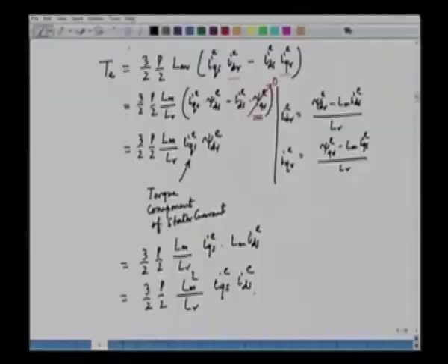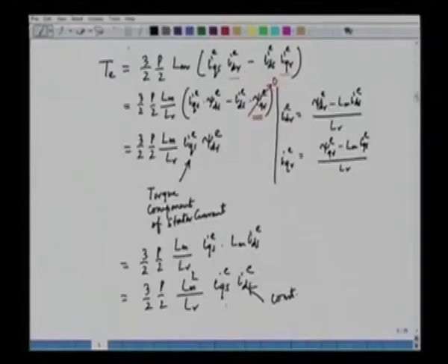we keep IDS constant, because if we change IDS, the flux will change, and if the flux changes, there will be a delay. So we keep IDS constant and we change IQS for the torque control. So the torque is controlled primarily by controlling IQS, because when we control IQS, there is no delay involved. So IQS can be controlled quickly and the torque will respond linearly to IQS.